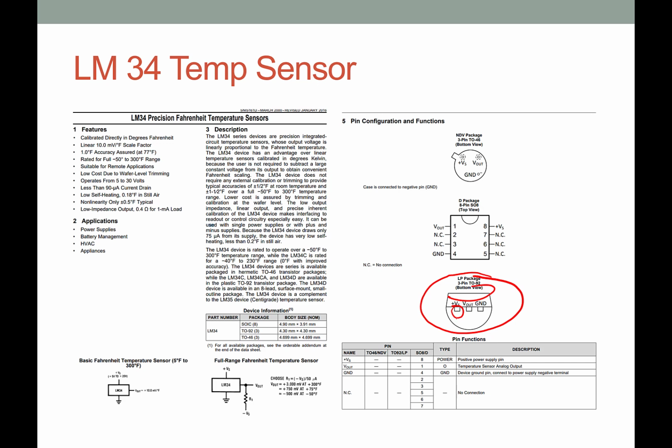For Vs, I don't think your board has 5 volts on it anywhere, so you probably need to use the 5 volts from the DC power supplies that are in there, and Jitendra can help you with that. That's not very hard, but just take the 5 volts to somewhere on one of the buses. They're similar to the DC supplies that you've used in circuits lab, so that shouldn't be a big deal.